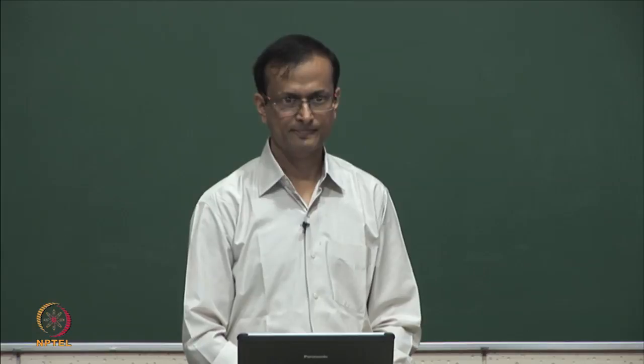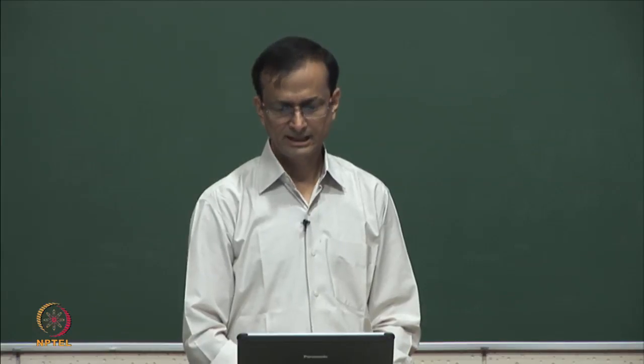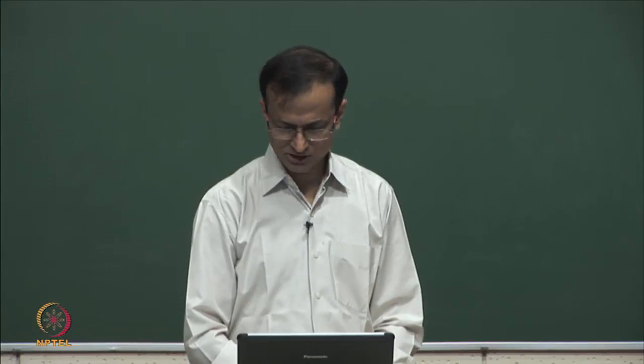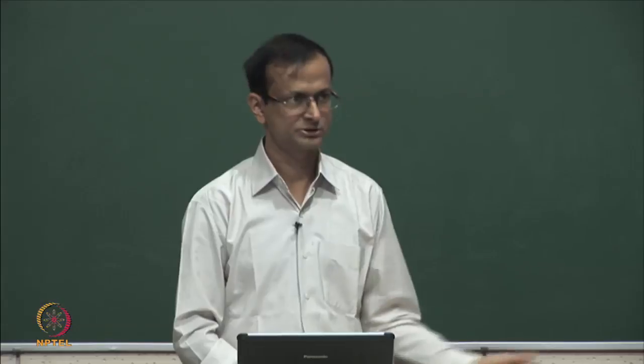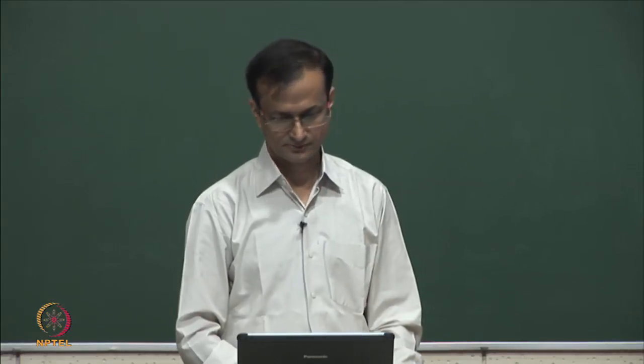The interconnection is the difficult one, right? Yeah, we did not talk too much about timing, for instance, here, and the timing is influenced by the route that the wires take. While this step itself might not be too complex, the place and route is a complex process that does influence timing in other technologies as also in FPGA.